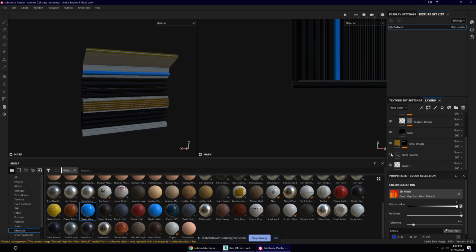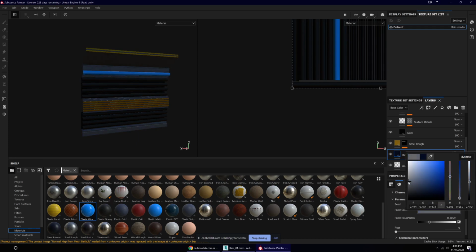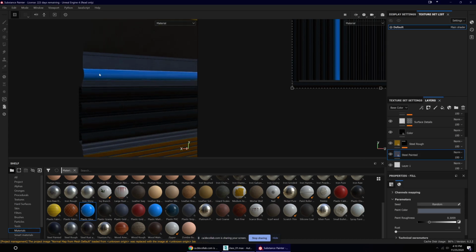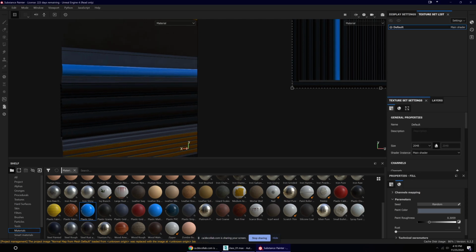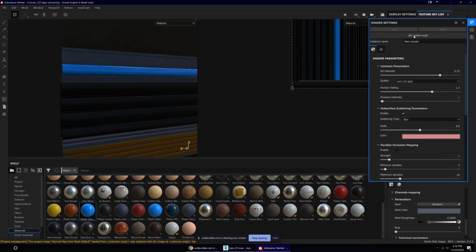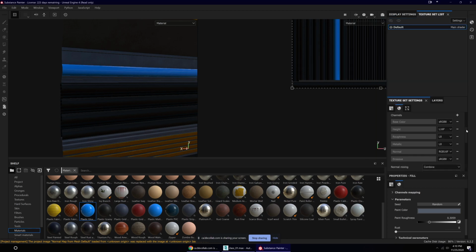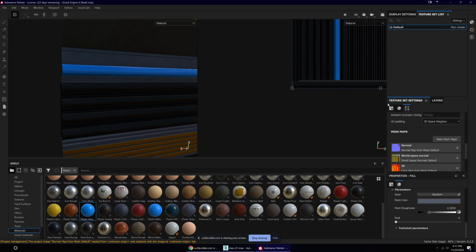All right, so let's see about this steel painted. Okay. So let's make this bar glow. What I'll need to do is add a new map. Channels, add, emissive. I need to go onto shader settings and change our shader to allow for that. Actually, on default, it does that. It's only for transparent materials you would have to do that. So yeah, emissive, that's working perfectly fine.